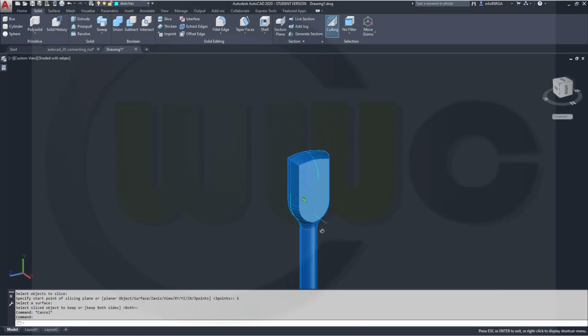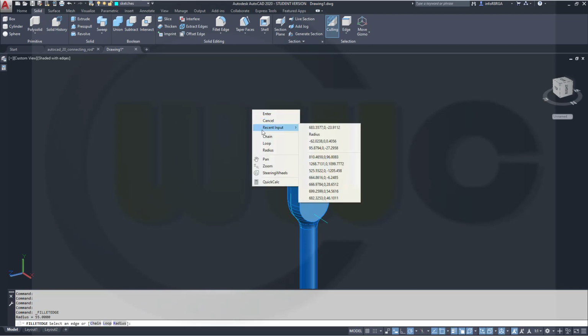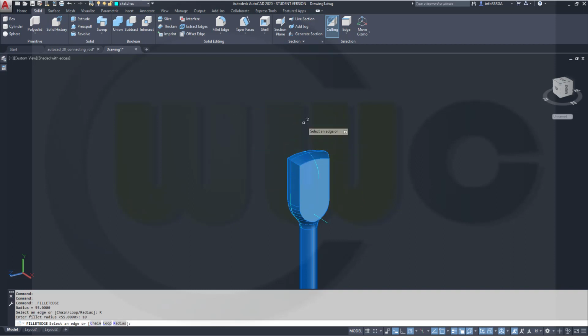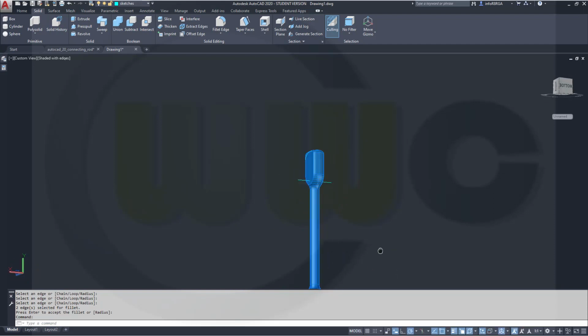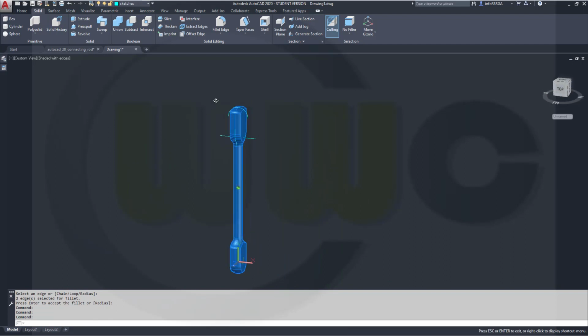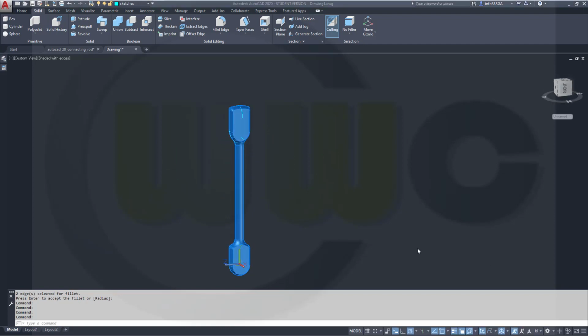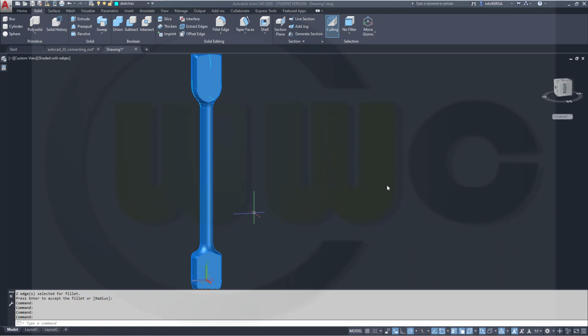Great. Now a fillet or 2 fillets, go for radius 10 here and there. Enter, enter. Great. Now I have to make the solids which I want to remove from this one, or I could do it with surfaces and slice it. So whatever you prefer. Okay, I will go for solids, at least at first, so go for the right view.